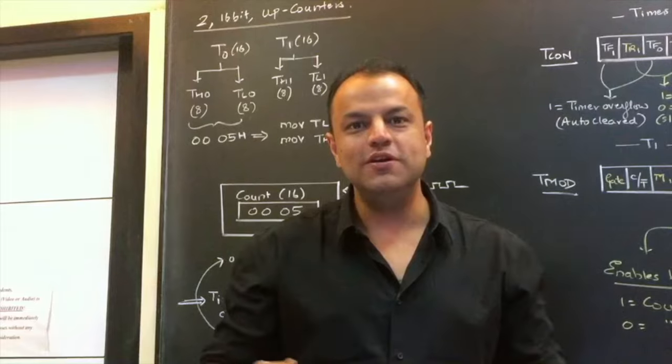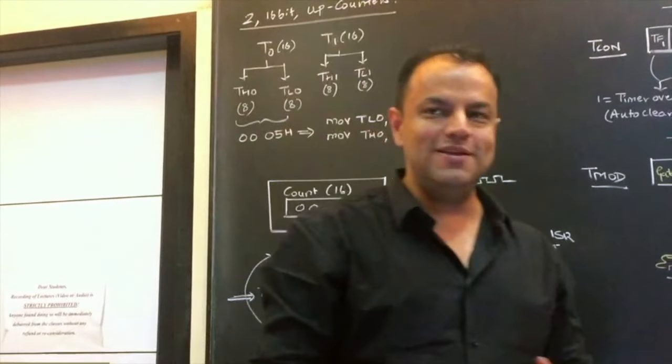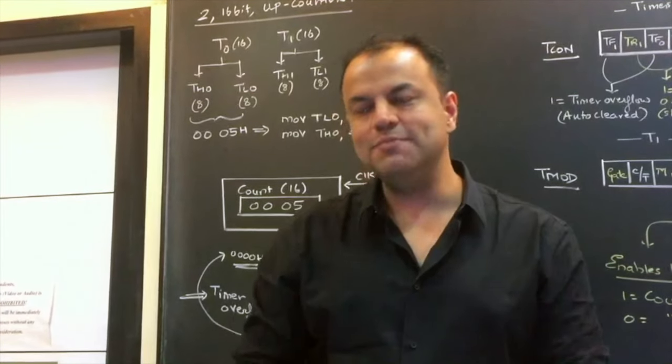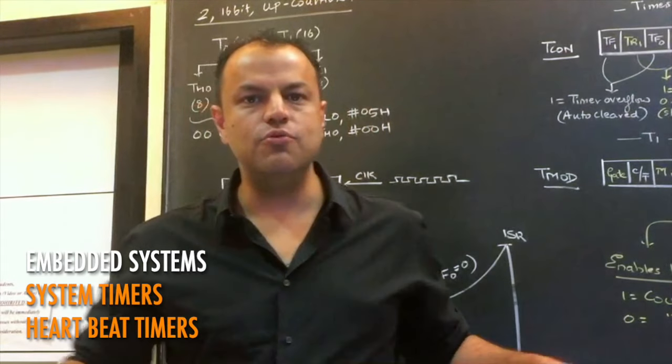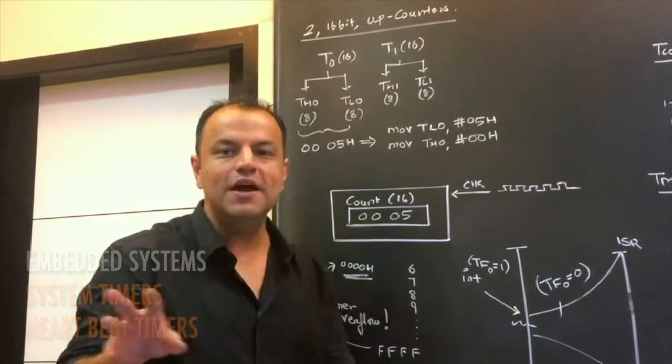The more timers you have, the more delays can be produced simultaneously. We could have had 30-40 timers also, but there is a limit to which you can add hardware to a chip. There are better ways to manage them, which you will learn when you learn embedded systems: how with the help of only two timers you can manage all your delays in a system. But that is a separate thing altogether, not here.